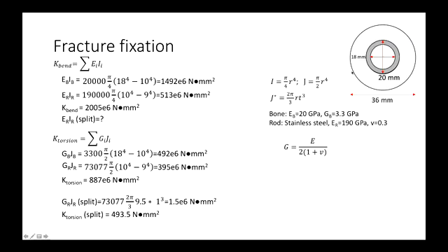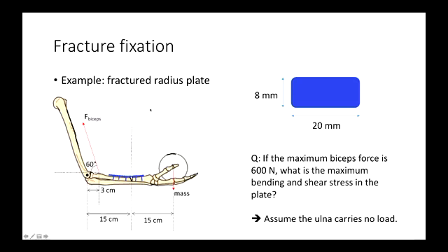But as I was saying, for relatively simple cross sections, and for bones, if you just assume it is like a cylinder, you can get some sort of estimates on your design, what's reasonable. Because quite often, from experience, when these plates get chosen, no one does any calculations. They just go, oh, 6 millimetres thickness is good. Yeah, seems reasonable.